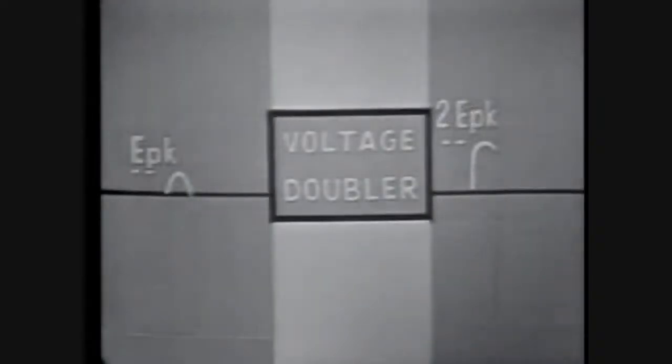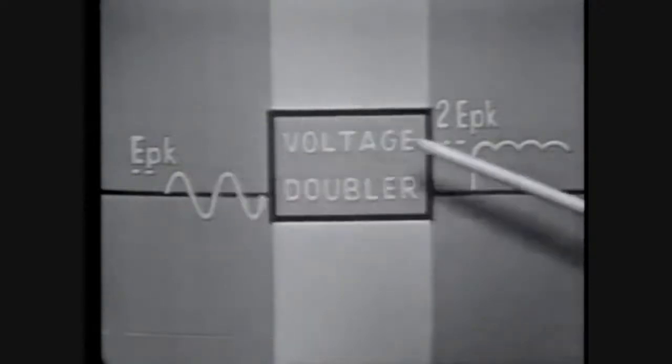One such application of the voltage doubler is in the high voltage section of this oscilloscope. The rectifying action of the voltage doubler is similar to that of other types of rectifier circuits in that it converts an AC voltage into a DC voltage. And it can operate as a full-wave rectifying device whereby it doubles the input to output frequency.